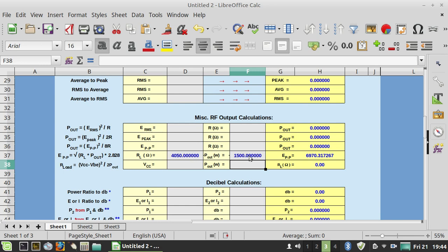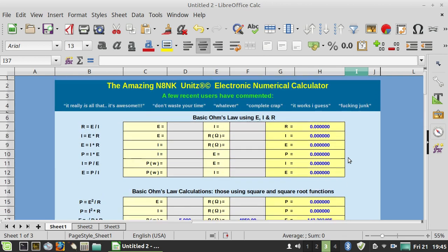Let's go back to QRP. Okay, so on the antenna terminal of the unun, we've got 402 volts, right? What kind of voltage should we see at the input, our 50 ohm coaxial input? 44 volts, peak to peak. Will you feel it? Yup. Yep, it'll give you a little owie, but just a little one.